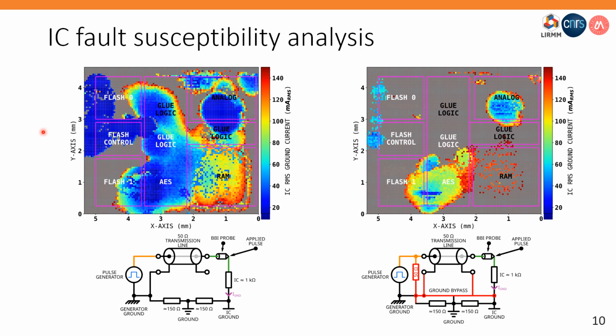This experiment allows spotting sensitive areas of the IC. At first sight, the most obvious difference between both scenarios is the drastic fault area reduction from the first to the second scenario. It might look like a downgrade from one platform to another, but it is not in fact. The ringing reduction easily explains the area reduction. Indeed, as we have seen before, the disturbances flowing through the IC are shorter and more precise with the enhanced platform. Thus, it reduces the area that the BBI is targeting and thus blocks further locations to fault at a specific location from the BBI probe, of course.